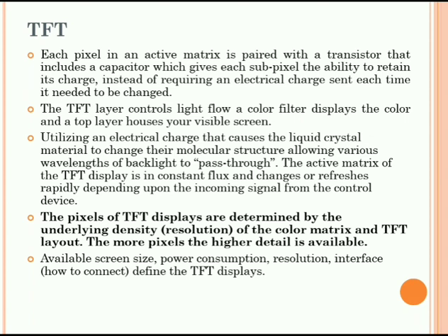In the TFT, each pixel is an active matrix. It is paired with a transistor that includes a capacitor, which gives each subpixel the ability to retain its charge, instead of requiring an electrical charge to be sent each time it needs to be changed.